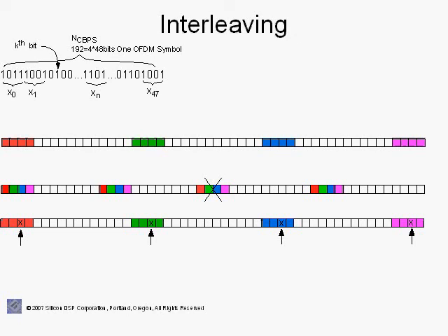But with interleaving and deinterleaving, we take those bursty errors and make them appear as random errors at the input of the Viterbi decoder, and the Viterbi decoder is quite capable of correcting those random bit errors, but not very good at correcting bursty errors. So interleaving and deinterleaving are integral to OFDM, especially in IEEE 802.11a and in IEEE 802.16-2004 and 2005, in terms of combining interleaving with forward error correction coding to achieve robust, reliable communications over wireless channels.